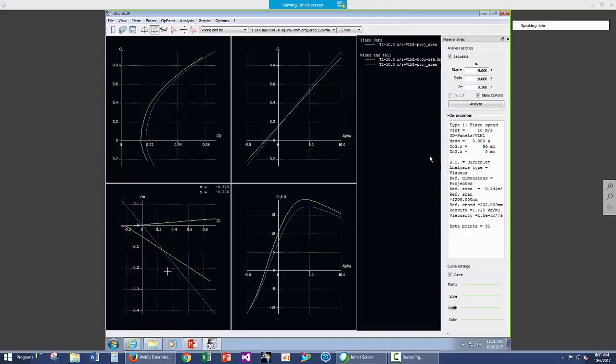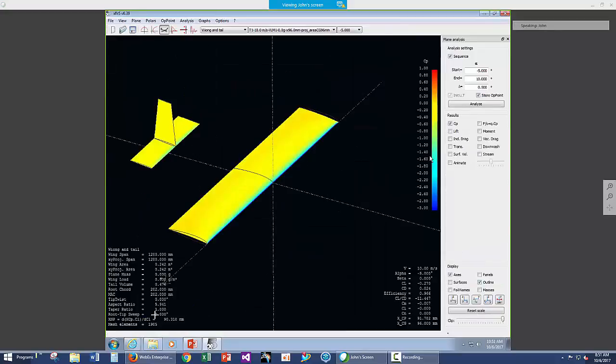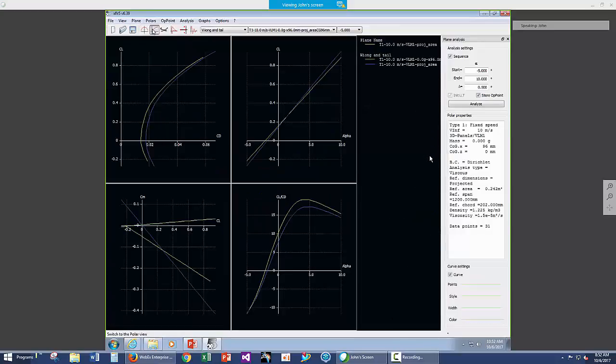Okay. Well, 96 was too much, and what I was trying to remember was this number over here, which was 90, not 96. So what we've got is not just a neutral airplane, but an unstable airplane. If I put 90 in there, it'll be horizontal. Let's do one more. What we want to do is put the CG somewhere in between, back maybe at 80 millimeters, and see what that does.